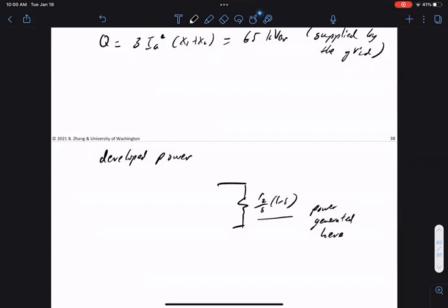Well, this is again just a resistor, so this is completely active power: 3 IA squared R2 (1 minus S) over S. The current flowing through it is IA. Square that, multiply by this resistance, and you get the power generated.